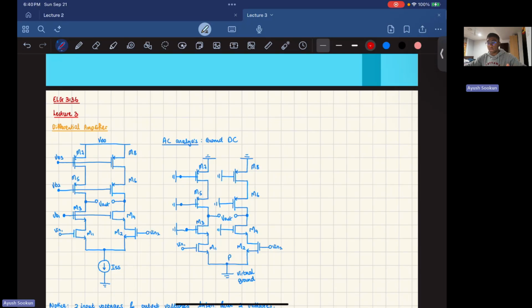If you remember from rectifier circuits, in Canada, all of the power we receive in our houses from the plugs is 60 hertz frequency. So that's the noise you're going to have in your circuits, because there are so many wires, like in your ceilings, wherever you work. It's all that 60 hertz frequency, and that's going to create noise.